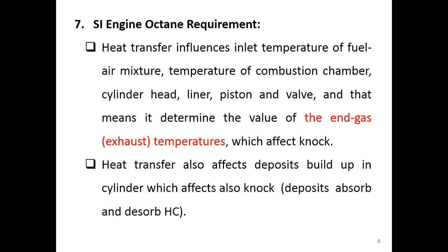If it goes out, your inlet air temperature goes down. So it affects this. It also affects what? The temperature of the combustion chamber, the temperature of the cylinder head, the temperature of the liner, the piston, and the valve.